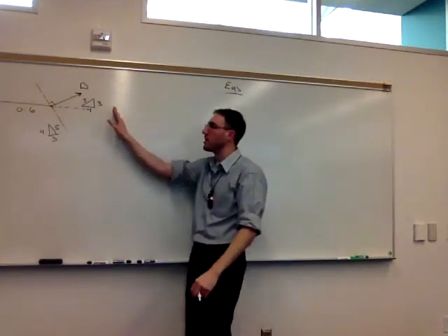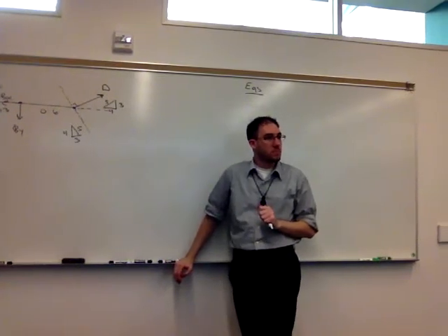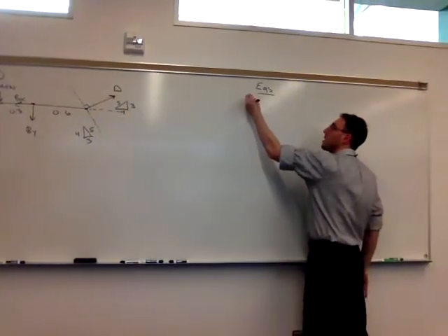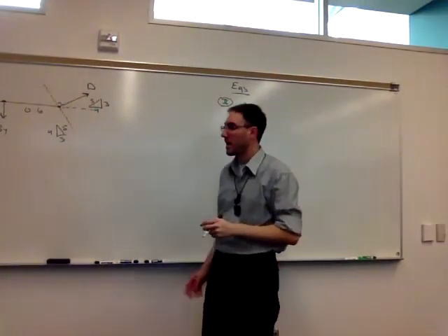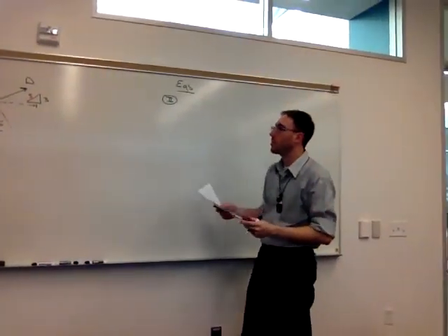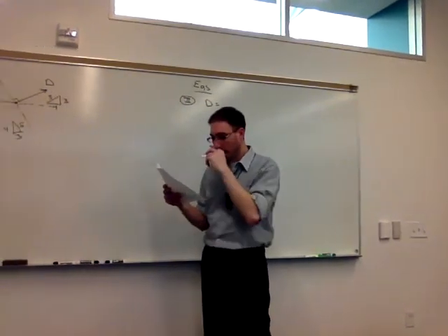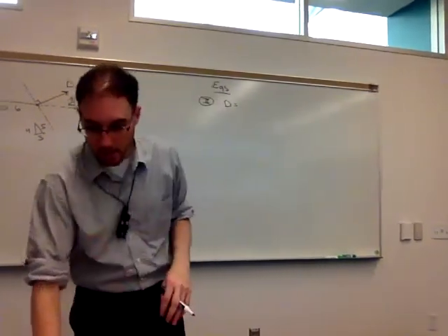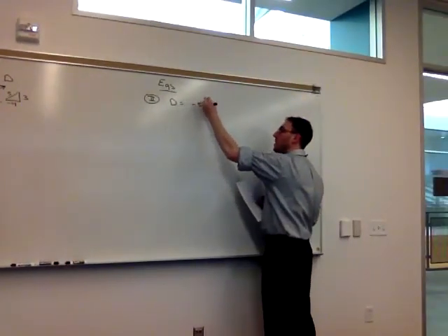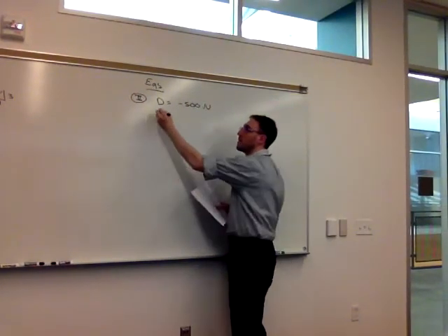Before I get to that, any questions on the second free body diagram that we drew? So looking at this one, there's only 3 unknowns, so I'm going to jump to the equation step and get what those unknowns are at this point, and then write more equations as I need them. So from free body diagram number 2, I can get the value of D if I take the sum of moments around B. The value of D turns out to be, my assumption, the way I drew it was wrong. It's actually negative 500, which is okay, because it could be up and right or down and left. It doesn't have to be a positive value.